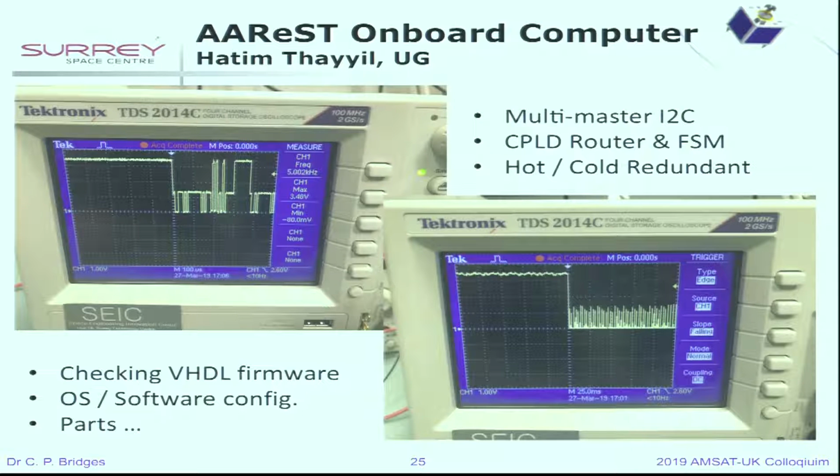And we use it as well to switch between things and to know how to control very small parts of that design. So our I2C FPGA doesn't just act as a router, it also is a switcher. It monitors heartbeats. It monitors the power levels. So a lot of the back switching that you saw on that complex PCB earlier actually has a lot of power monitoring circuitry itself to then know if something has happened.